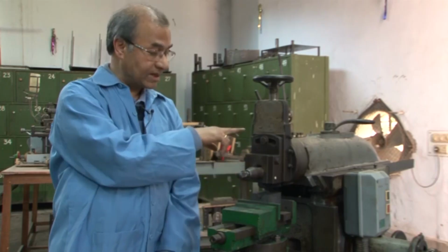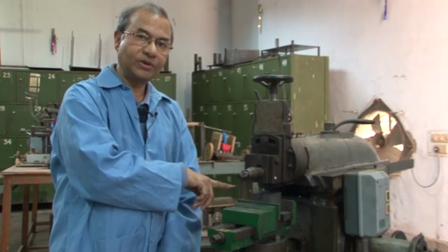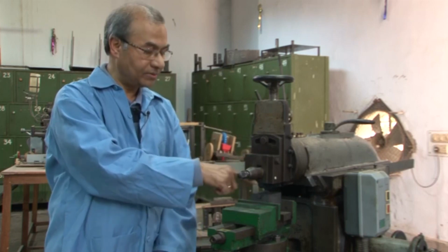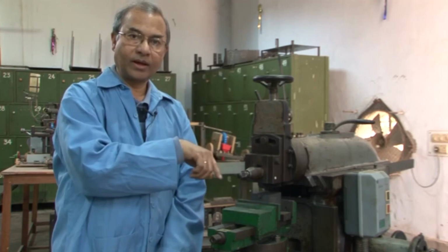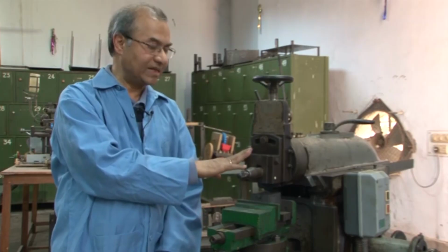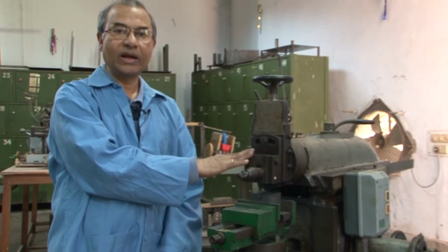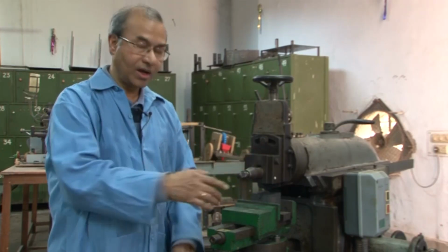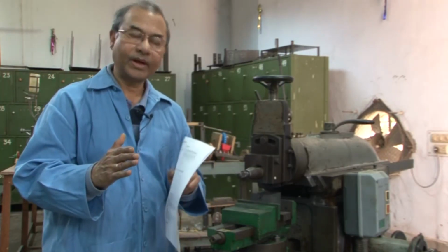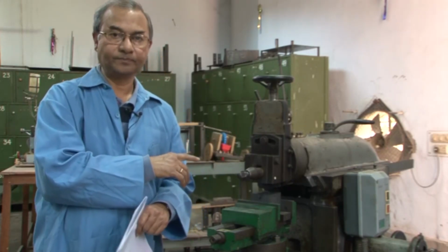During one stroke, that is the forward motion and the backward motion, the workpiece is given the feed, which is perpendicular to the direction of the actual movement of the tool. Actual movement means the cutting movement, the cutting speed. So, the cutting speed in this case will be the stroke of this tool. The stroke length can be changed depending on the length of the flat surface that you are covering, and that can be done with the help of a mechanism we are going to show you right now.